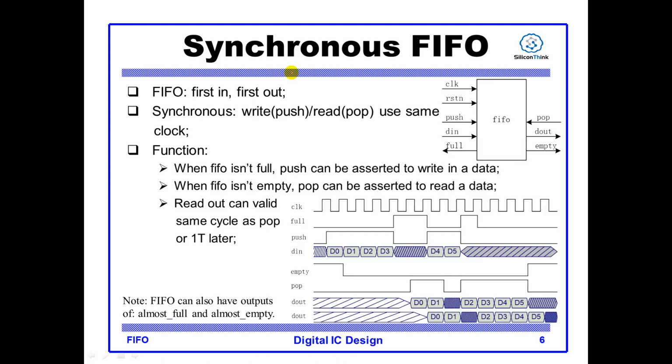I want to add one more point for synchronous FIFO. From the function of FIFO, you can see the protocol here and the protocol here is something like the handshake interface. Yes, the push and the full is something like the handshake interface, and the pop and empty is also something like the handshake interface.